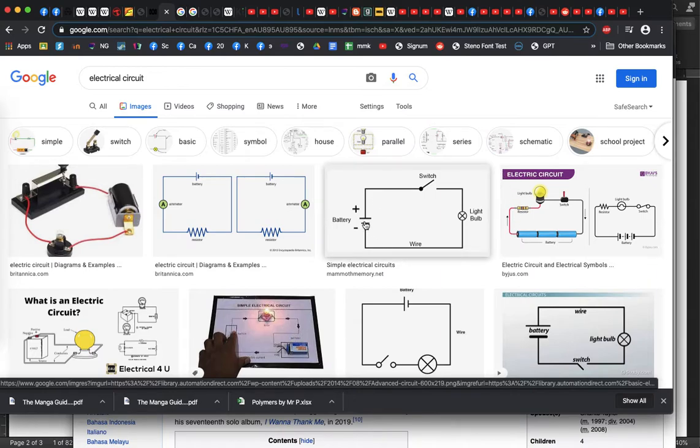What we draw is the battery as a big line and a little line with a gap in between. The convention is that we draw the big side as positive. How I remember that is that the big side takes twice as much ink. It takes twice as much ink to draw a plus sign as it does to draw a negative sign. Now, what's interesting is that the current goes from the positive to the negative. That seems like the exact opposite of what I just said, where the electrons flow from the area with too much negative charge towards the positive charge. Well, current flows opposite to the flow of electrons.